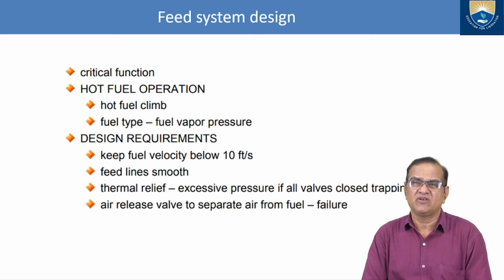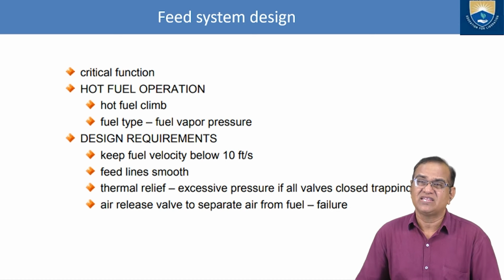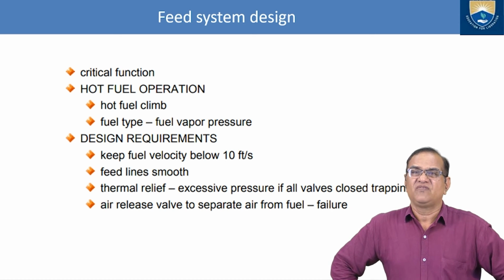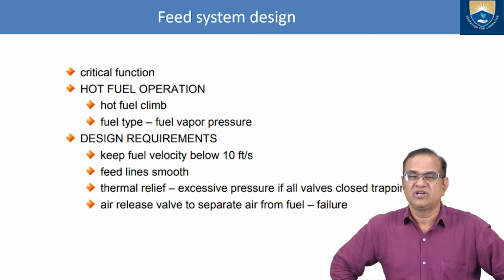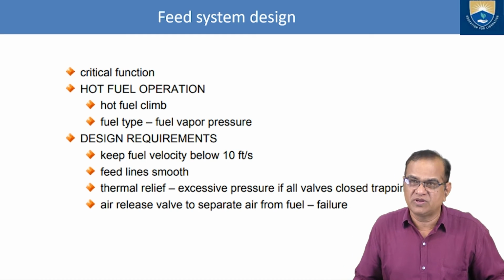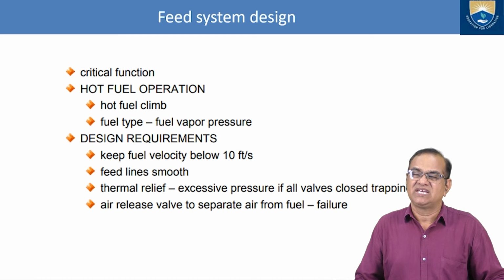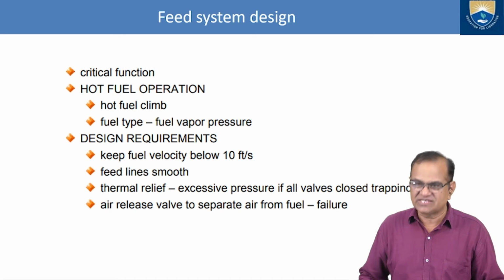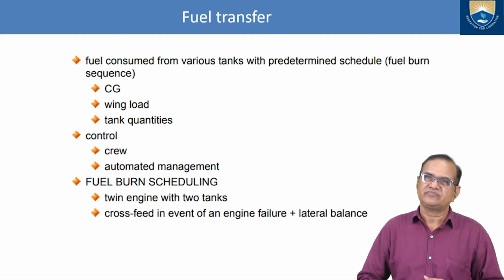The fuel velocity should not be very high, otherwise it will create problems for the pumps and all. Feed line should be very smooth. A thermal relief valve should be fitted, which senses the pressure and the temperature, and closes and opens the fuel valve. Air release valves separate air from the fuel in case of any failure.